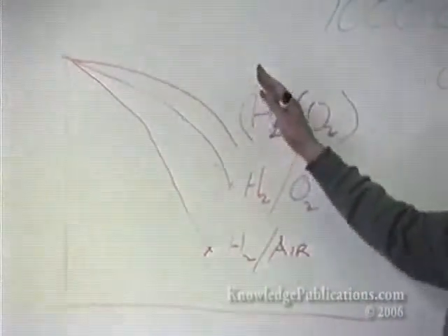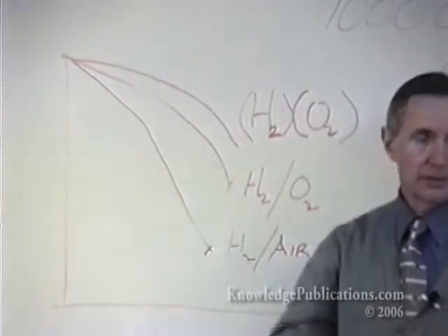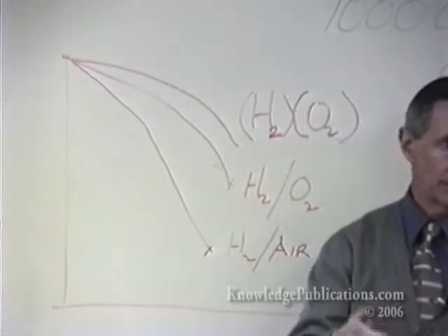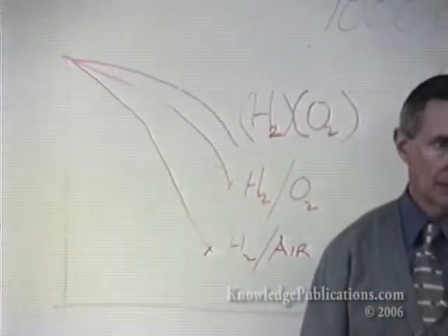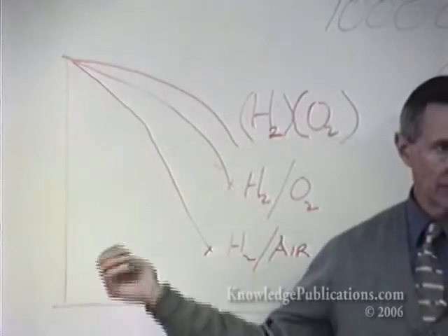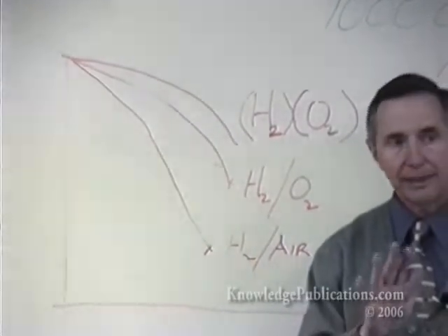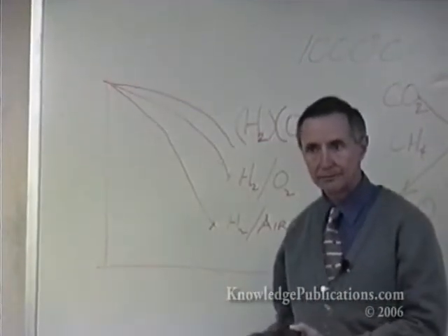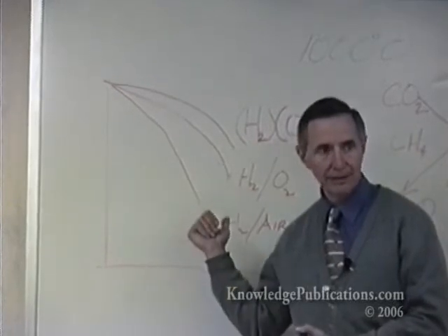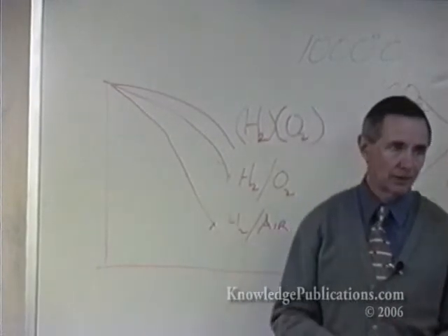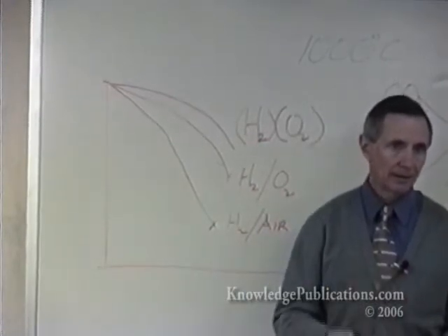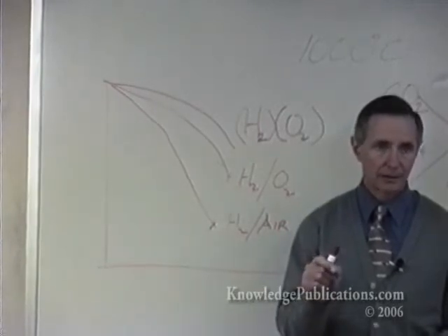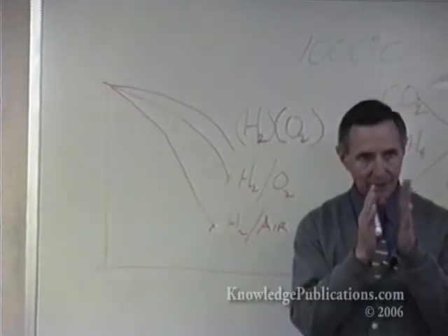For most economic analysis, you'll find that the industry is looking at about a 30% efficient fuel cell on American numbers, that is, using enthalpy as the denominator, or using produced voltage as the numerator compared to 1.48 as the denominator. That means 70% of the energy that you put into the cell has to be taken away as heat. Or you start melting down something, or you change the operation internally if you have that heat build up that is the 70% that isn't going into electricity. Big numbers in terms of what you have to do in small spaces.